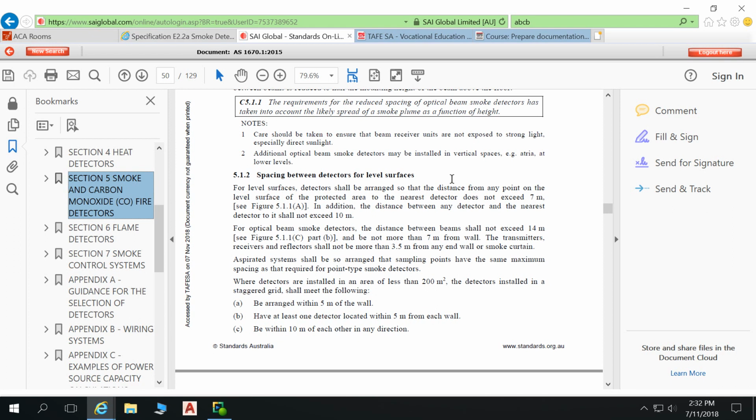But the other important points I covered on Monday was that you have to have fire hydrants, and because our only access between the 2 floors is a fire isolated stairway, you're not allowed to be bringing fire hoses through a fire isolated stairway. That's because they jam the doors open. And if someone's fighting a fire and they realise, no, we can't get this out, and they just drop the hose and run out, that door won't close, fire spreads through the building.